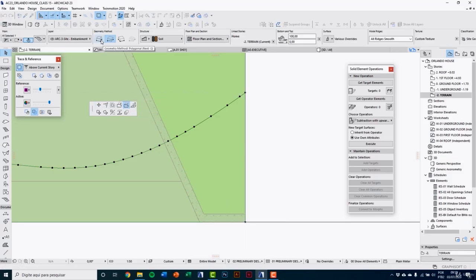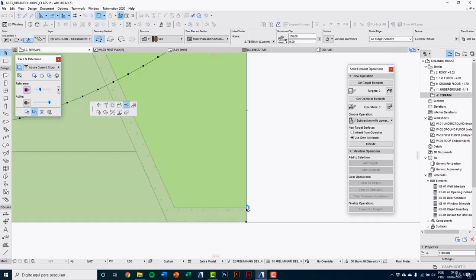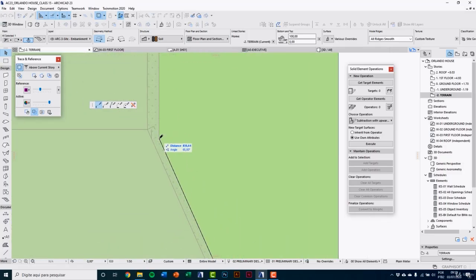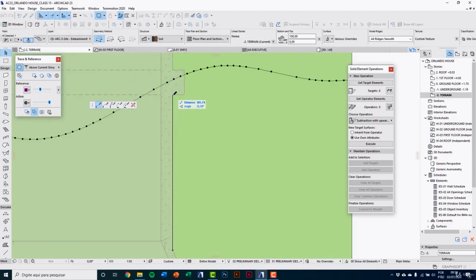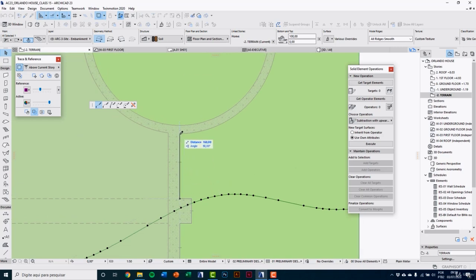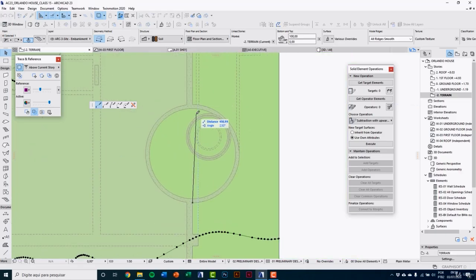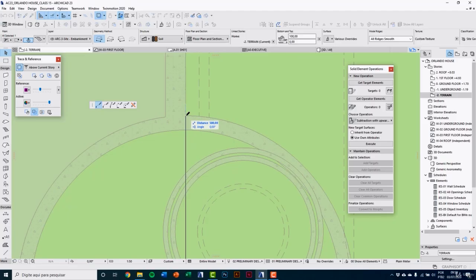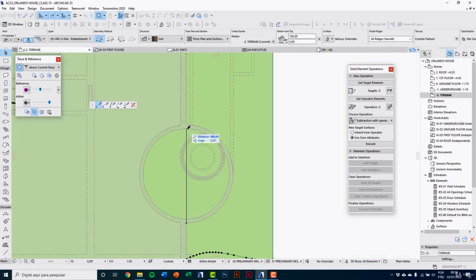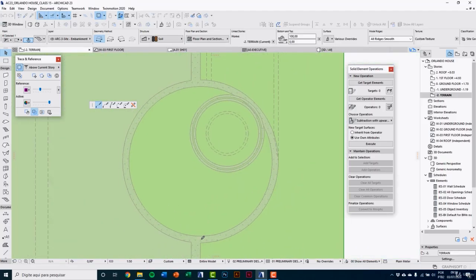Using the polygonal geometry method here, do the polygon picking the external side of the retaining wall. Here in this curved part, it's easier to click on Start and End Point, and after, curve the edge. So I will click here, external side.